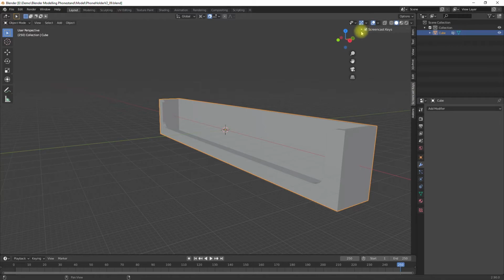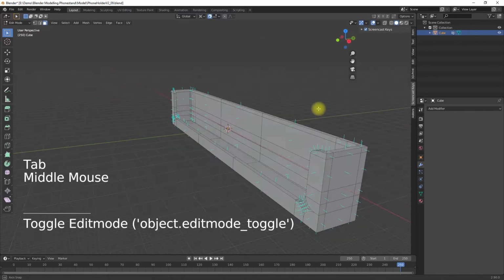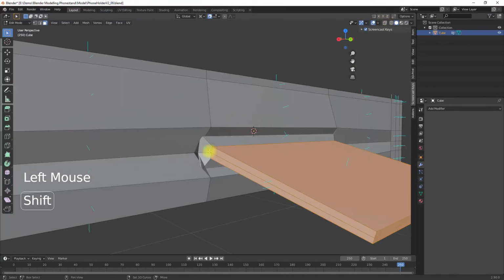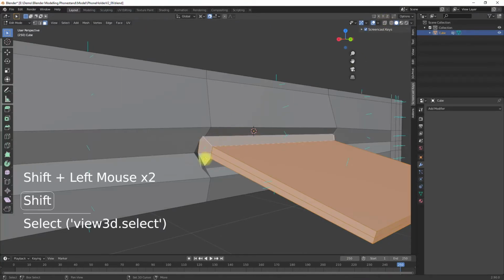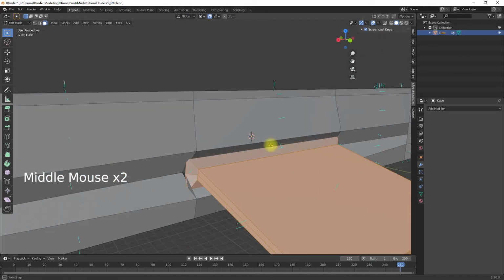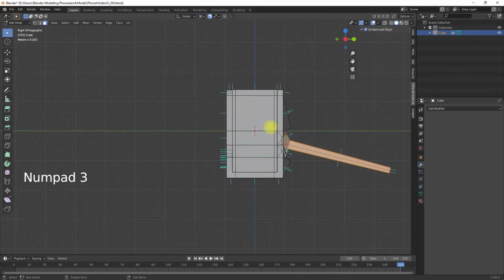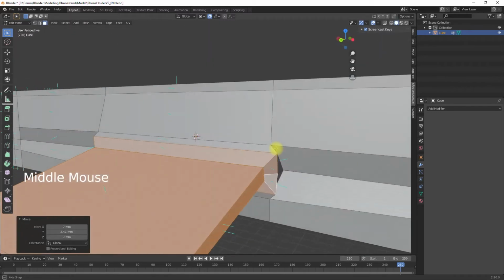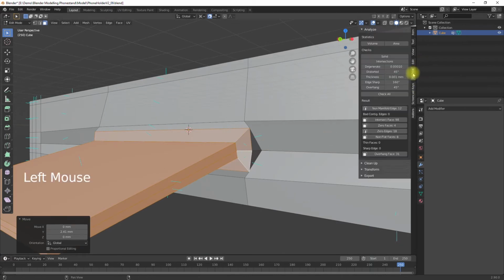Our goal was to design a model for 3D printing. For this purpose, any errors in the model must be removed to complete the design. The add-on 3D Print Toolbox offers some tools for this, especially to find non-manifold areas or non-planar triangles in your model.